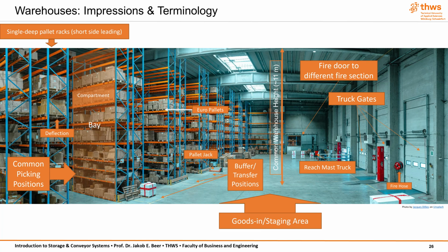They are generally more resistant to sudden breakage, but they tend to deform permanently under sustained pressure, especially if overloaded or exposed to high temperatures. Some specialized pallets are made of metal, which can reduce deflection but are heavier, more expensive, and less common in standard warehouse operations. Finally, deflection depends on how the pallet is supported.